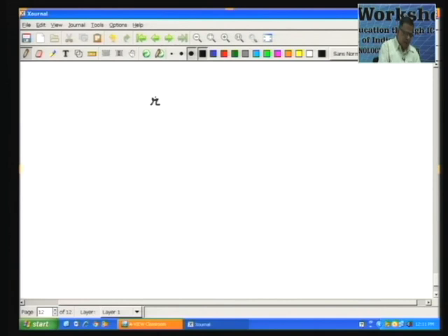Now, if you look at RCP cross F, we can write it as this determinant, where in the first row you write I J K. Then in the second row we will write the components of the first vector RCP, and in the third row we will write the components of F. So, now RCP has components XCP, YCP, and the ZCP is 0.